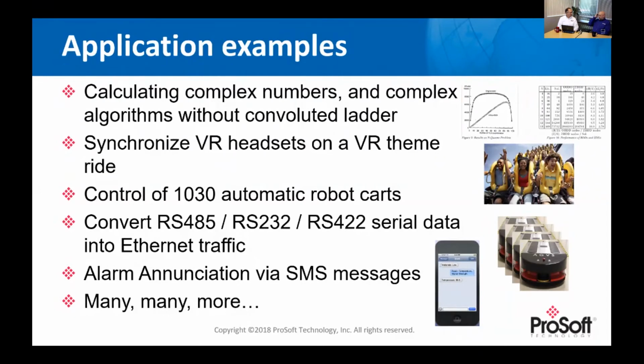If you had a ControlLogix chassis with no processor, and you put the LDM module in there, it will power up and act as a Unix machine, and you can access the Ethernet ports and the serial ports and all that, but you're not connected to a processor, so you're kind of limited on what you can really do at that point.